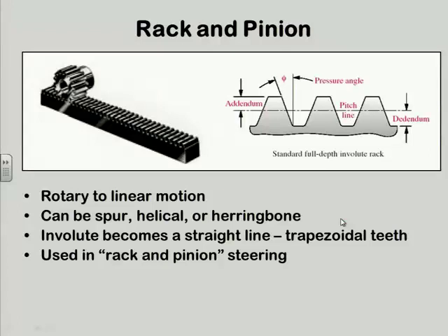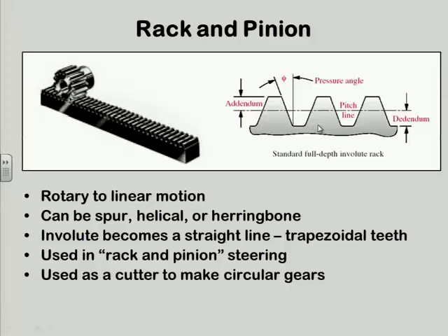Very direct steering. Its big advantage, and why it's desirable, particularly in sports cars, is it's very directly connected. The option is to use a worm and wheel. Most other cars, if they don't have rack and pinion, they've got a worm at the end of the steering column and a worm wheel in contact with that, and that's turning a lever, which is the input to your links to go over to the wheels and turn them. And since worm and wheels have a lot of backlash, those cars may have a little bit of play in the wheel and not be tight. Whereas the rack and pinion, if it's done properly with very little clearance in here, can have very, very tight steering.